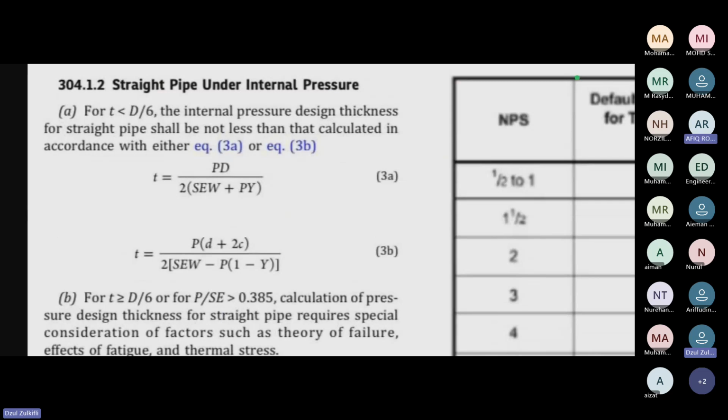It depends on the size of the stiffener ring. Okay, so Part 4 has guidance on what size of stiffener ring is allowed to basically not be considered as a discontinuity, they call it. Okay, so to be honest, in my experience, the ring has to be very big for it to not be able to do FFS. Most of the time, it should still be okay.